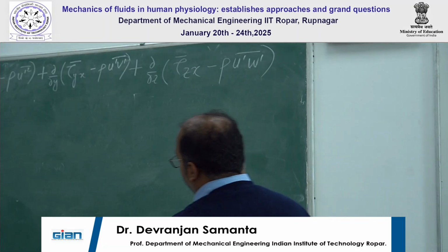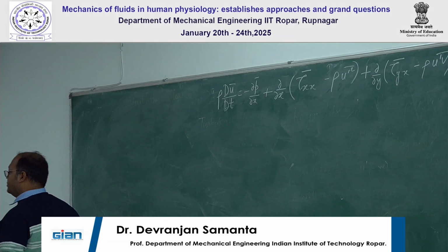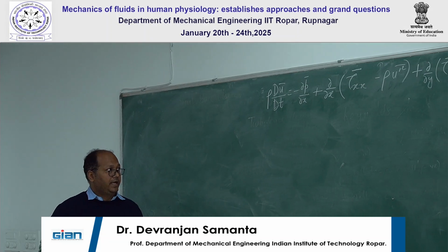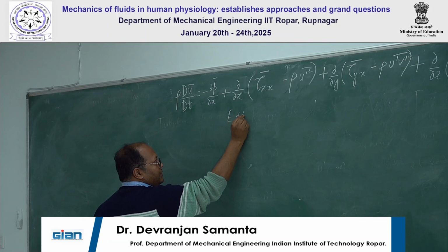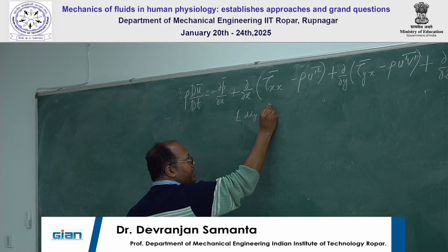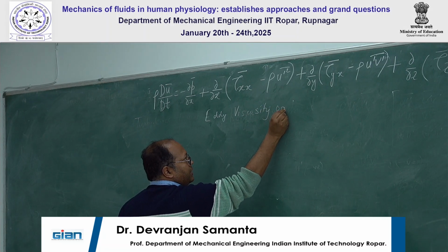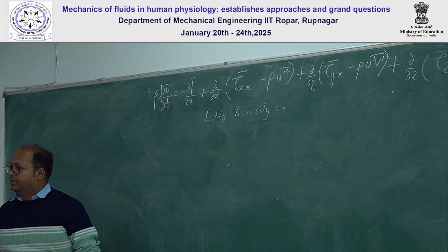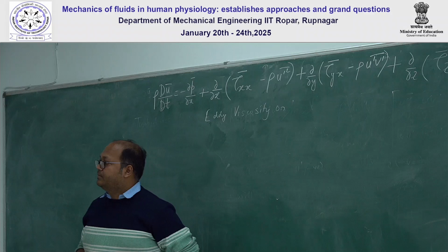So in order to tackle the turbulence closure problem, we introduce one term called the eddy viscosity or the turbulence viscosity. We will show now how it is coming. So eddy viscosity or turbulent viscosity is not a vector property. It is just to counter the turbulence closure problem, and will be denoted as mu t.